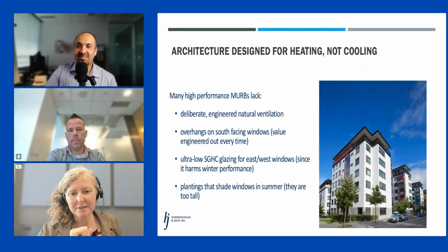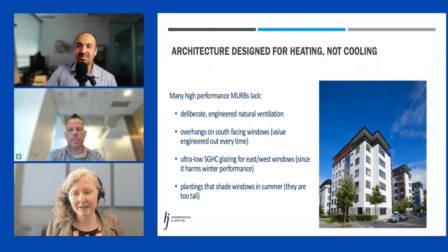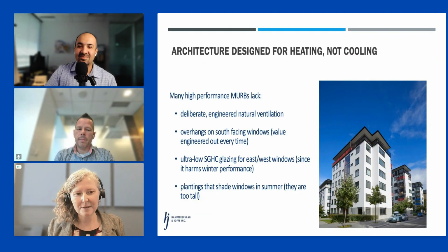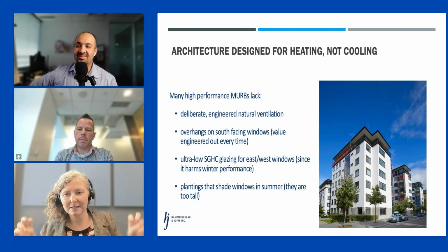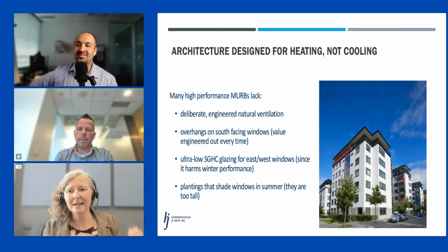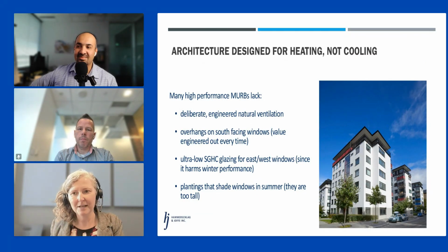The other major challenge we are seeing in these high performance buildings with these facades that look just like what Scott presented is that with all that insulation and these windows that we don't have money to put overhangs over, and these tiny little balconies that we've deleted, we don't have south facing overhangs, and we are gently incentivized to increase our solar heat gain because it looks better in the model because it heats the building for free in the winter. But it does that at the expense of a life safety challenge in the summer if you have a cooling outage and you've got the sun coming in the window.